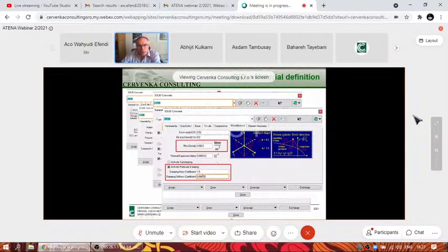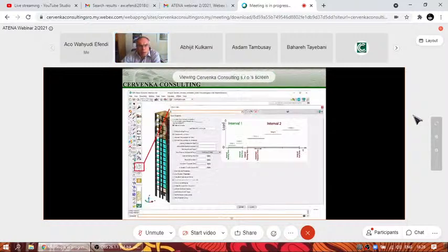If you do that, then this will override the previous definition of the damping, as I mentioned, in the problem data dialog. So that original, global definition will be used for the whole structure, with the exception of the materials where particular damping is activated. Important part for dynamic analysis.